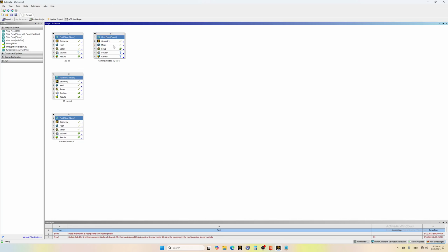Okay, if everything is fine, you have a check mark here, but Ansys Workbench has a bug. Sometimes the mesh seems to be alright, so you have the check mark, but when you try to import it in Ansys Fluent, it will throw an error and crash. Don't worry, that means you have to go back to the mesh and see if the mesh is alright, so you change the meshing. Most probably you have to change from multi-zone to Cartesian mesh.